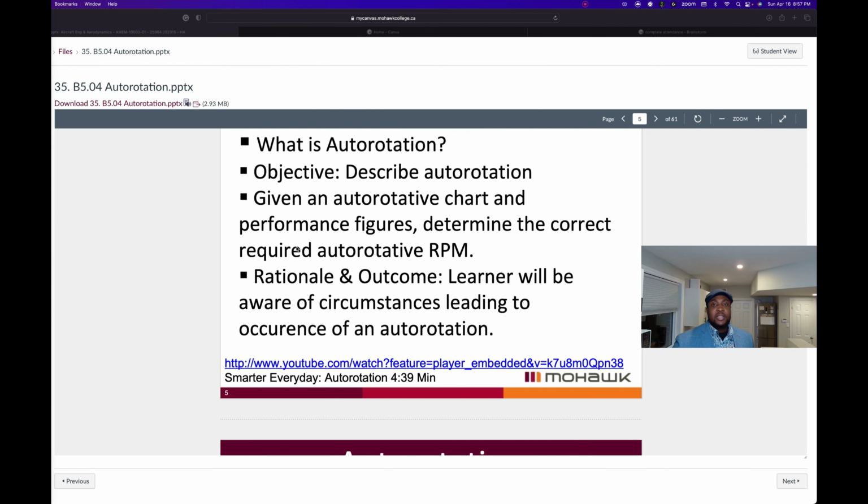Maintaining rotor RPM throughout autorotation is very crucial in order to have a successful autorotation. Once the collective is lowered fully for autorotation, the adjustment is continuous to maintain proper rotor RPM until the helicopter is safely on the ground.